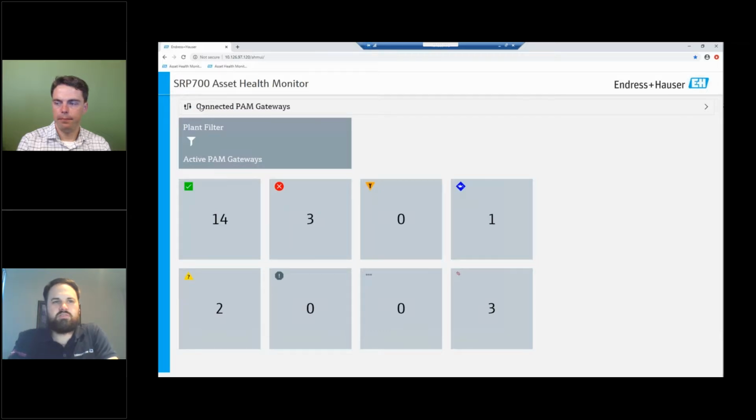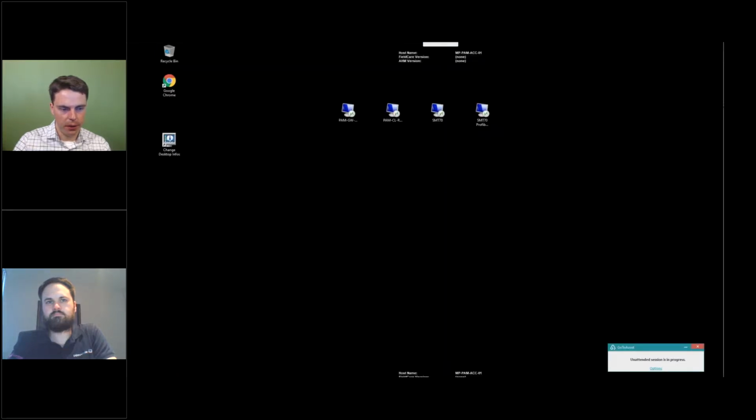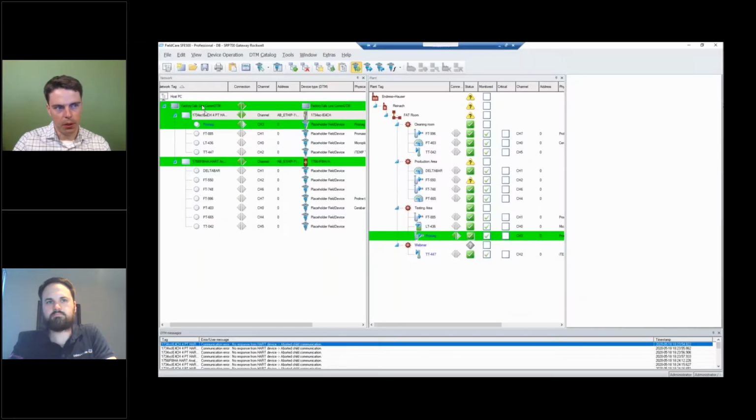We've got a question from Jerry. He asks, can the client and server be in a VPN network and therefore work in multiple remote locations? This depends a bit on the technology we're using. If the communication driver files that are used to connect to the system, so if I go back to the server, here we're using the Rockwell FactoryTalk DTMs. If those are suitable to be connected with this kind of technology, then yes, but it needs to be tested.